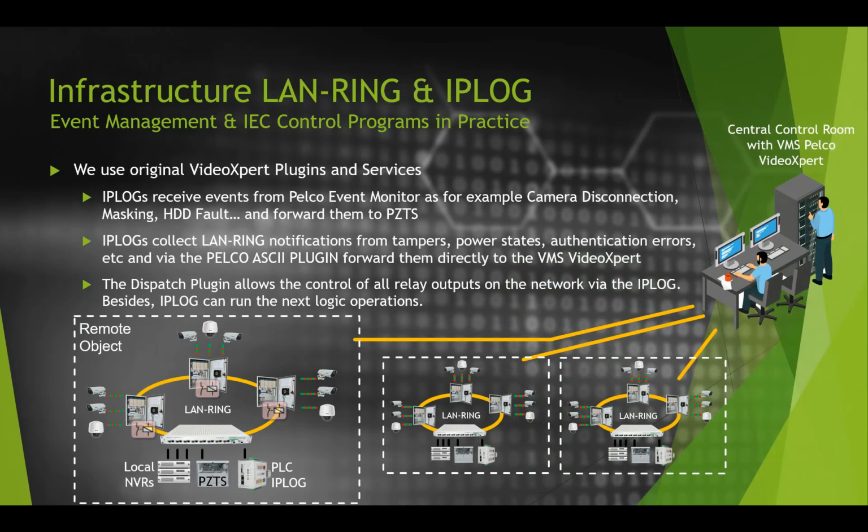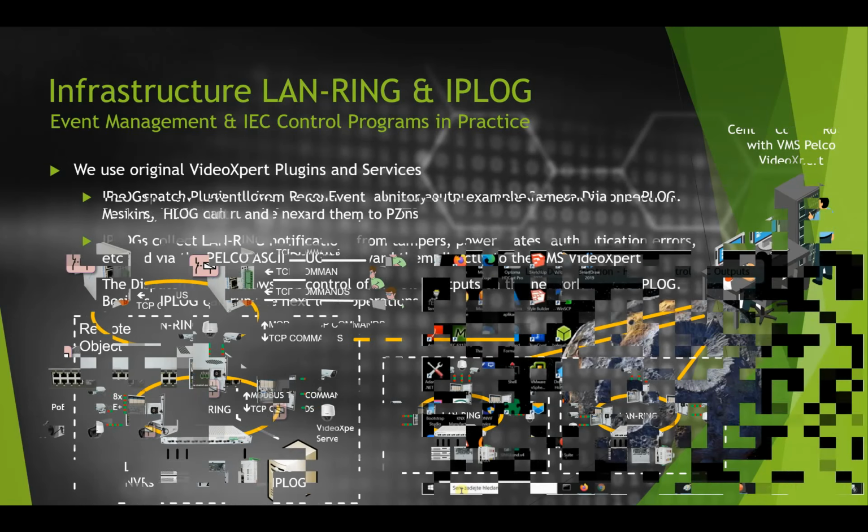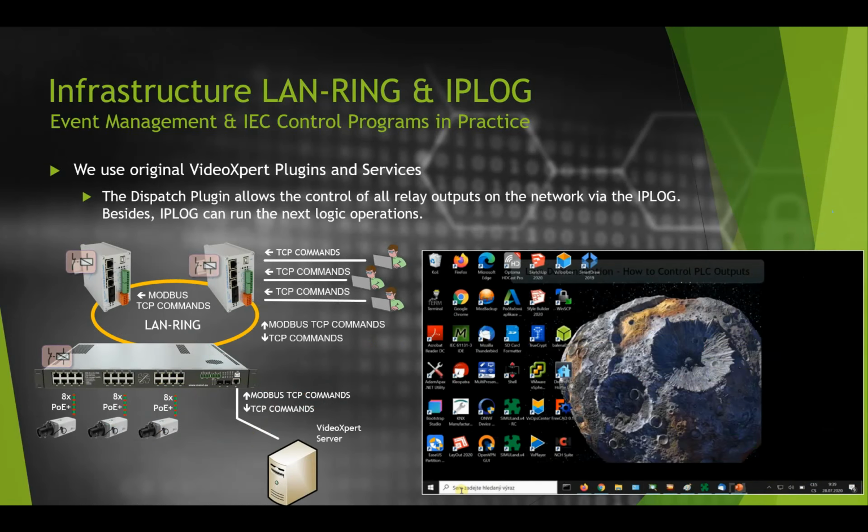For example, tamper statuses, power, 802.1x authentication errors, and so on are passed directly to VMS VideoXpert via the Pelco ASCII plugin. The system operator can then control our relay outputs through the Pelco dispatch plugin.